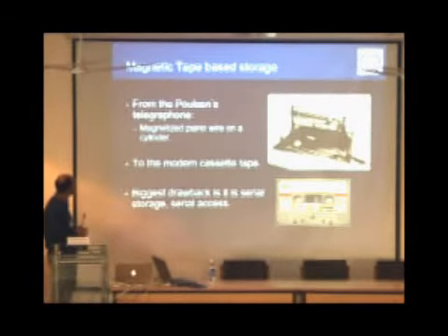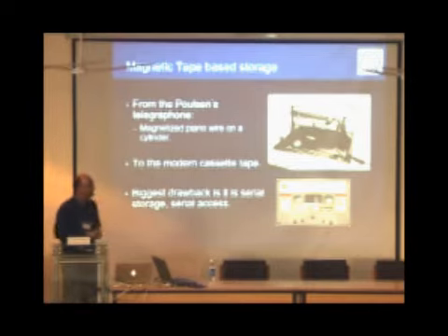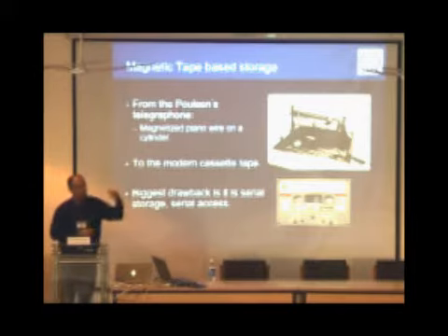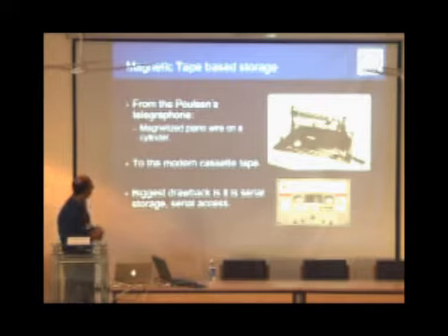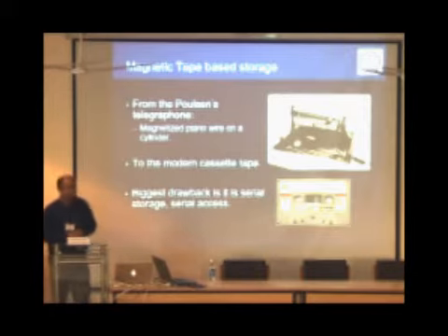One of the first storage mechanisms was iron, actually iron oxide. It's an iron wire wound like a rheostat on a spiral coil, and the top surface of the iron gets oxidized, so it becomes iron oxide. By applying very high fields from an inductive coiled head, you can magnetize or demagnetize parts of the wire. So this is a very early form of storage.